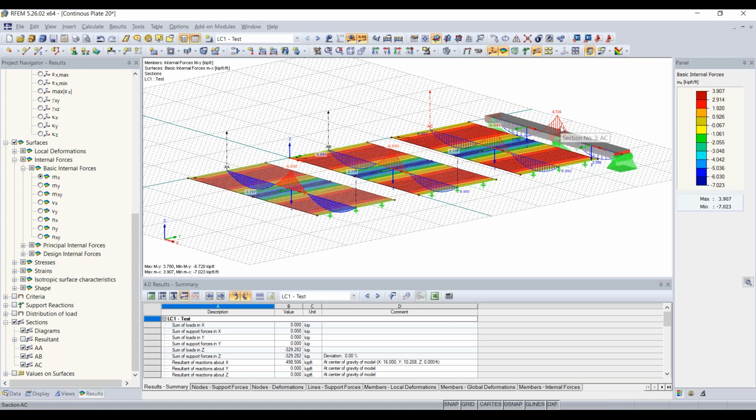And the reason that this change happens is because the methods mostly used in school assume that each member has an infinite shear stiffness, when in reality there are some shear deformations happening when members or beams bend. So it's important to keep this in mind again when comparing hand calcs. Based on shear stiffness, I just want to go back to the PowerPoint, and we can start talking about plate theory. This will make more sense once we get into it. So I'm going to switch back to the PowerPoint.